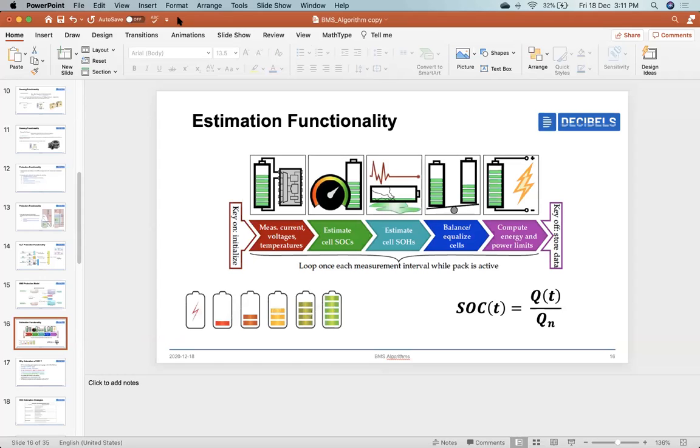If you go over 60, it's called high voltage. It requires a lot of high-level protections, like isolation monitoring systems and stuff like that. So it is not easy to manage such a system, from a safety perspective and to ensure functional safety.